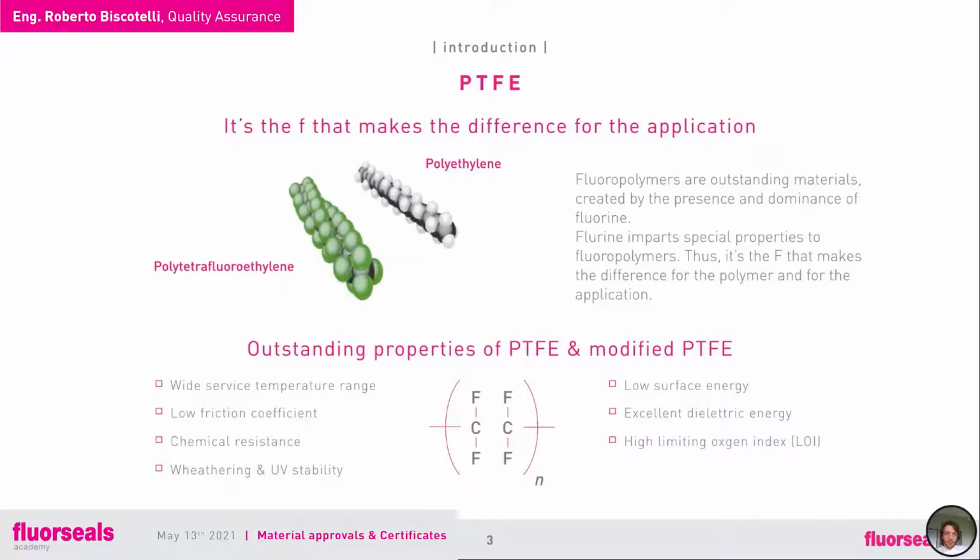So a little bit of an introduction to the PTFE world. As many of you already know, PTFE has many unique properties, and this is the reason why it's applied in a wide variety of different applications, different industry with different requirements. PTFE chemical resistance is top-notch. It's basically impervious to every known substance, with a couple of exceptions, so highly reactive alkali metal, like sodium, potassium, something like that, and very strong fluorinating agents. And this is already very aggressive media. Generally speaking, PTFE is an extremely inert polymer.